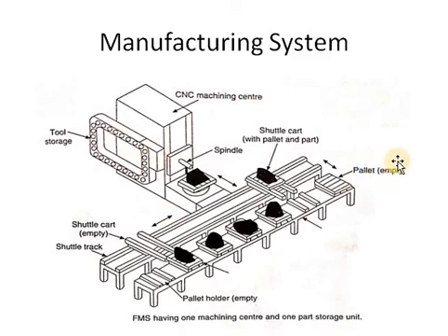The inspection stations are introduced into flexible manufacturing systems either by including an inspection operation at a given workstation, or by designating a specific station for inspection somewhere else. The coordinate measuring machines, special inspection probes that can be used in machine tools, and machine vision represent three methods of inspection in a flexible manufacturing system. The sheet metal processing machines consist of press working operations such as punching, shearing, and bending and forming processes. That could be, you can say, the manufacturing system.